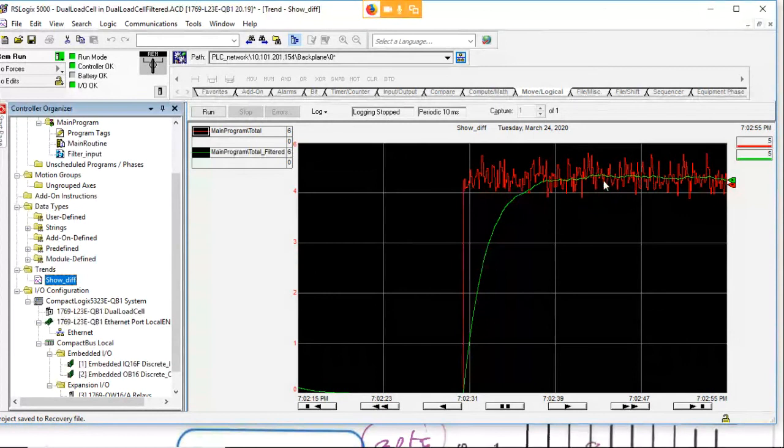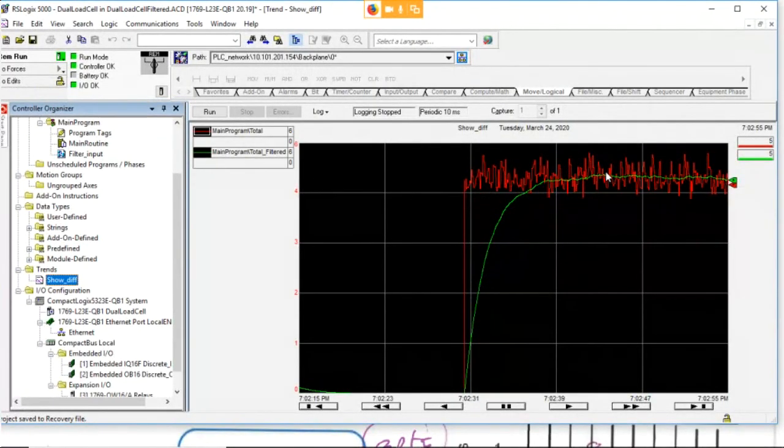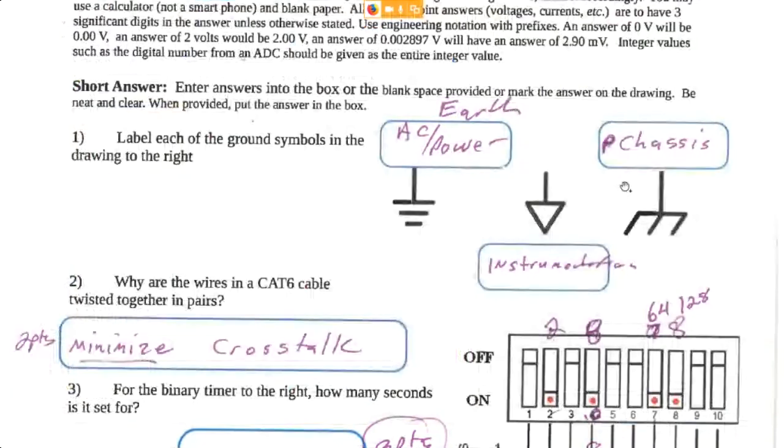So the weight isn't bouncing around. The weight's just sitting there. There may be slight vibrations in the building due to how noisy the air vents are in C205, so there's some vibration that might affect that. But all this very high bounce in this red here comes, I think, from the fact that it's a switching power supply, so it's a very noisy power supply. I'm working on trying to buy some new ones that aren't quite so noisy. Anyhow, we want to have all our high current stuff running to a separate ground to help minimize the noise.